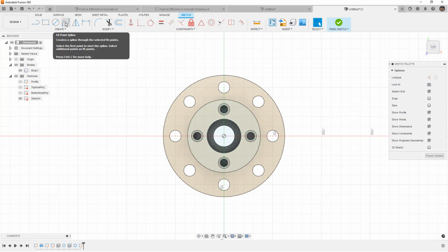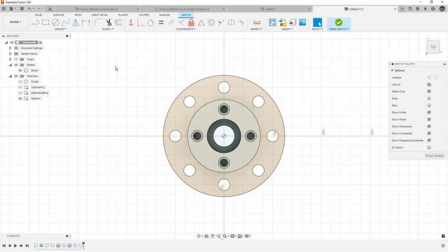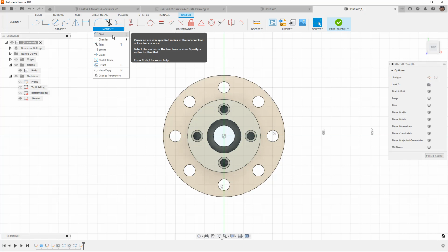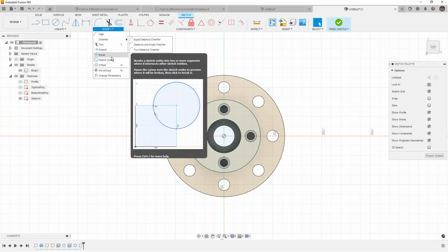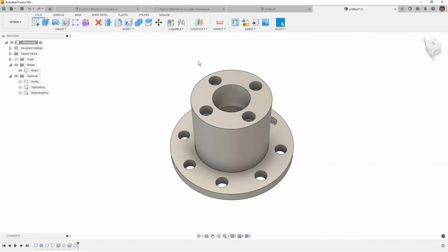I used to use splines and surfaces quite a bit, so I would have the spline as a shortcut key. I used to use P on the keyboard for that because P is the project command in Fusion, which again, I use that one quite a bit. I don't tend to do a lot of fillets and sketches or chamfers, so I don't really use those. Trim and offset I don't really use, but I do use move copy quite a bit. So getting comfortable with these different shortcuts can speed up your modeling approach.